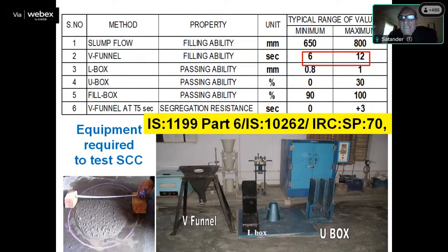I think we are deleting this portion, the use of slag in the bituminous mix. The reason is that there is sometimes sulfur. If sulfur is not there, you can use slag provided it conforms to all the aggregate specifications. Now we have put this in the revision, because I am a member of that working group where we are revising the MoRTH book also.